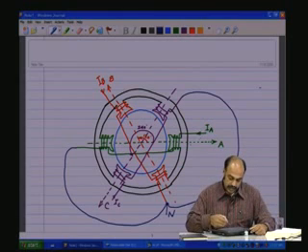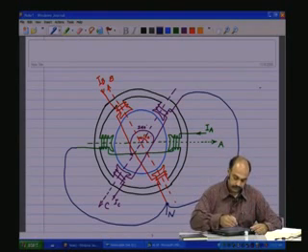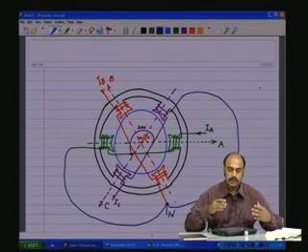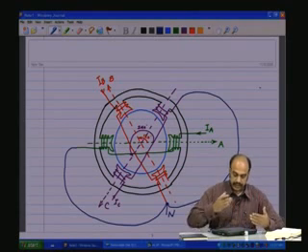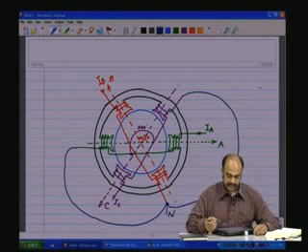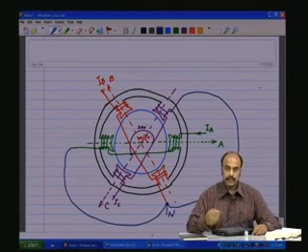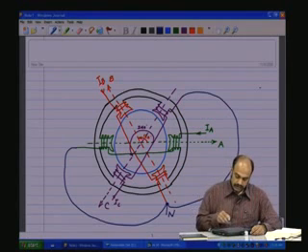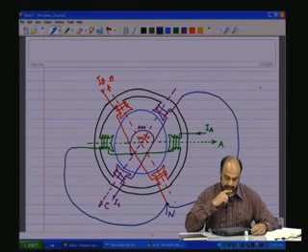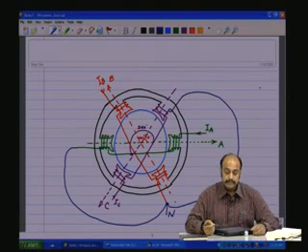flowing. So IA is flowing through the A phase pole, this is stationary, fixed, and IB is flowing through the B phase pole, that is also stationary and fixed in space, 120 degrees shifted with respect to the A phase pole, and IC is flowing through the C phase pole, the C phase axis, and that is also shifted 240 degrees with respect to the A phase, this one, in this manner. So this is a star connected induction motor. The stator coils are star connected with the currents IA, IB, IC flowing in this manner.